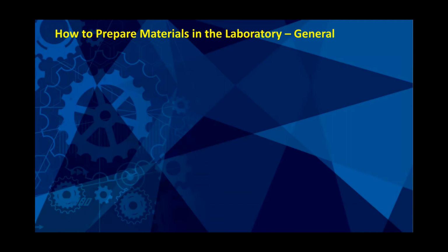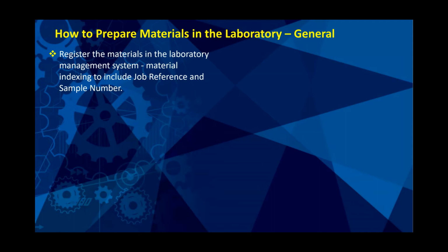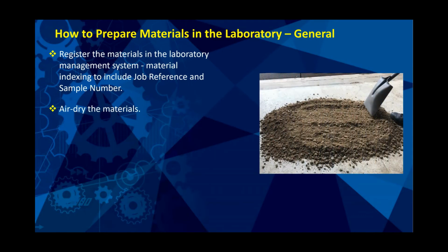In the following, we'll go through the general procedures for preparing materials once you have brought them into the laboratory. You first have to register materials, and the material indexing system should include a job reference and sample number. You then have to air dry the materials.